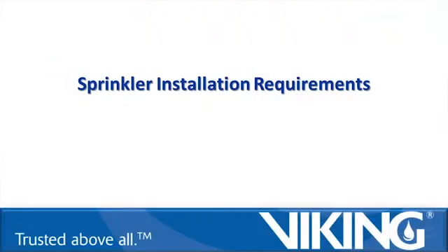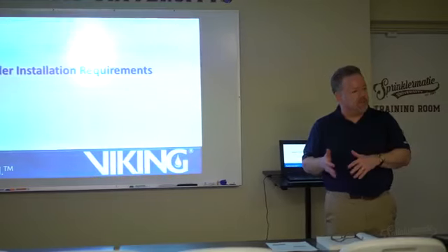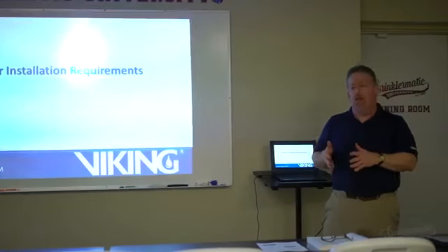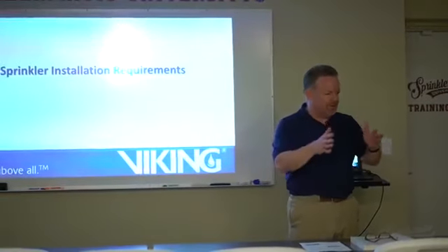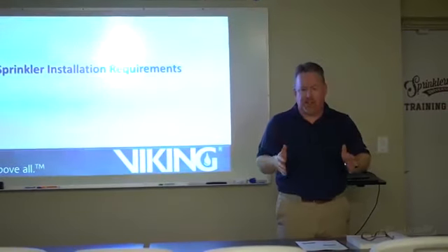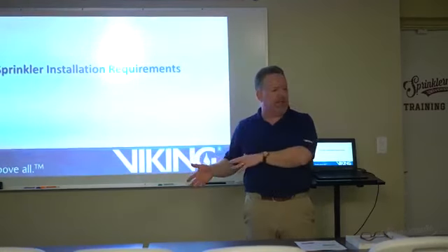Basically, what we're going to be doing is building on the presentation, just kind of an introduction to sprinklers, but now we're going to take it to the next level and focus specifically on the installation requirements that come from Chapter 8. We're going to walk through Chapter 8 in the standard, which is the installation rules. Chapter 8 is divided into a couple of overview sections, and then it gets specifically into the installation requirements for each type of sprinkler.